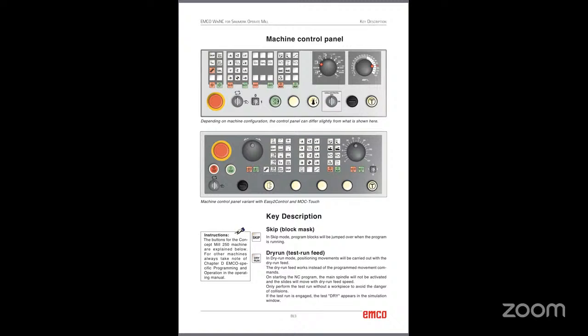So remove the workpiece, and this is our program, right? Now I'm going to check. So now this is dry run. First, second step. Now you can see the spindle is not rotating, right? This is your control, and on the machine there is no spindle rotation. So dry run. So go to simulate.